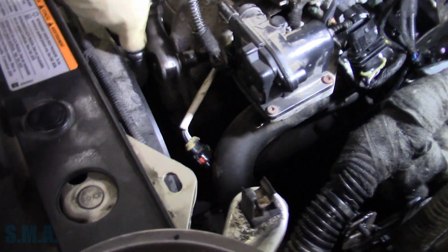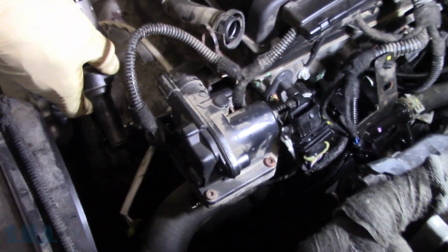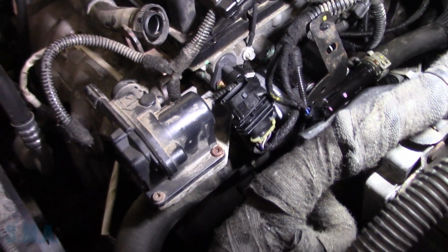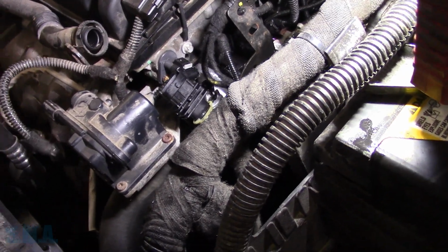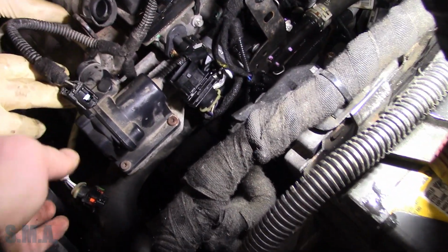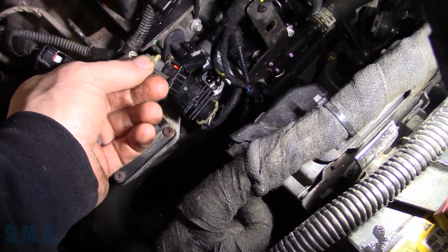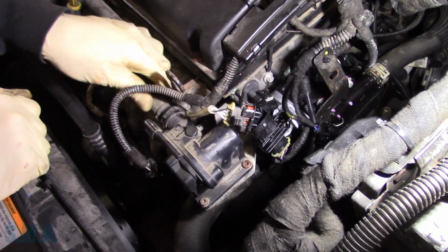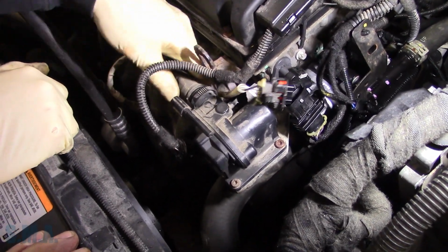Yeah, so now he's putting the diverter valve back on. Like I said, what are there, 3 bolts in that, Jay? Yeah, 3 bolts. Gonna torque them to spec here before we're done, of course, naturally. I unplugged all this for you. That came up and around here. That's for the O2. Out there, right? Yep, and then you got the air pump connector there.